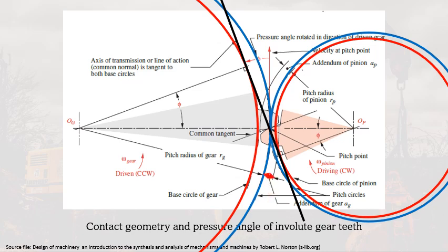The difference between the upper part of a tooth and the pitch circle is the addendum, so it's the excess. Same also for the addendum of our pinion. In the design they are actually equal, but since we also include some clearance, that's why they have some difference in the measurement of the addendum.